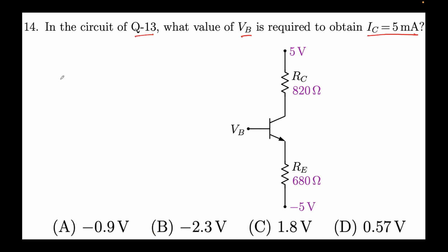Now if you recall what we talked about in the very first problems related to BJT, I wrote an expression for the active region. This is the expression that we had seen for active region for BJTs. At room temperature, the thermal voltage will be constant at 26 millivolts. I naught depends on how you fabricate the BJT, which for all practical purposes will remain constant for us. The only thing that we can play with is VB and VE, and to be more precise, their difference. If you change their values, and also the value of VC, you can change whether the device is in active mode or saturation mode. We saw the onset of saturation, problems like that. So VB is important in that aspect.